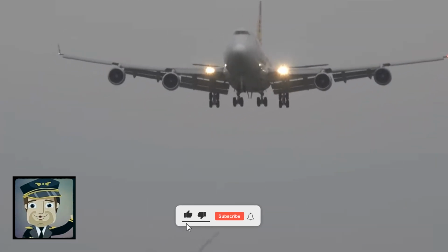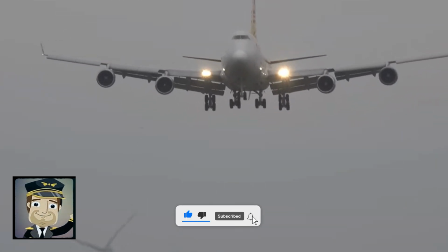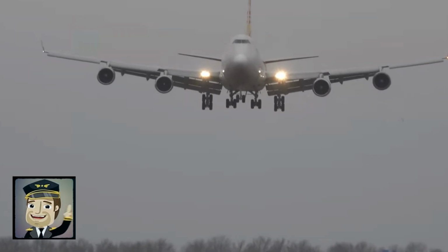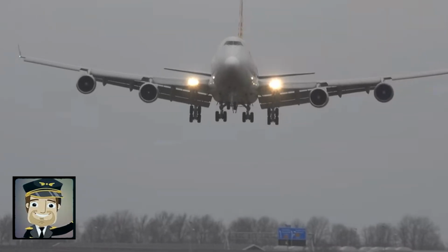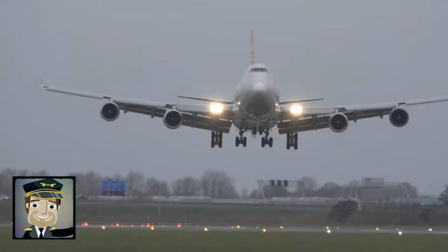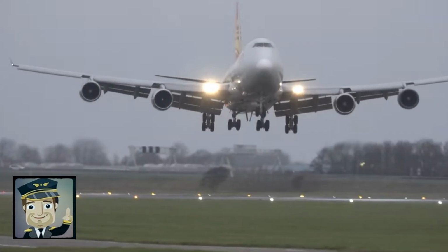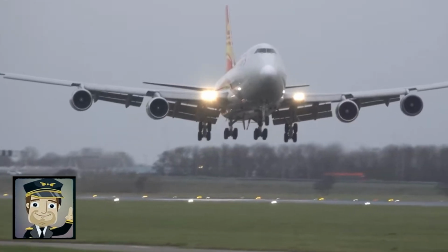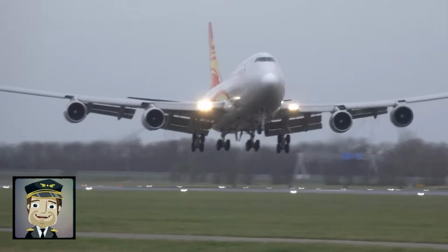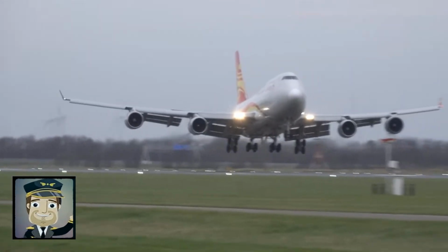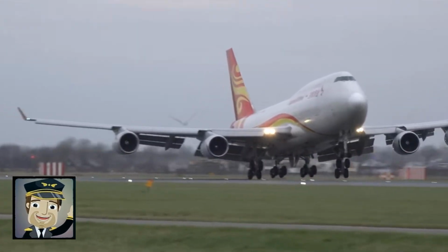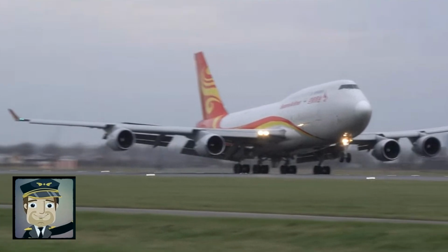during landing. It is important to emphasize that each aircraft has specific crosswind limits established by the manufacturer. These limits, usually expressed in knots, are strictly respected by pilots. For instance, large commercial jets may have maximum demonstrated crosswind limits between 30 and 40 knots, while smaller aircraft withstand much less. Operating beyond these limits not only compromises safety, but may also damage the landing gear or other systems. Therefore, in extreme situations, a pilot may decide to divert to another airport with better conditions.